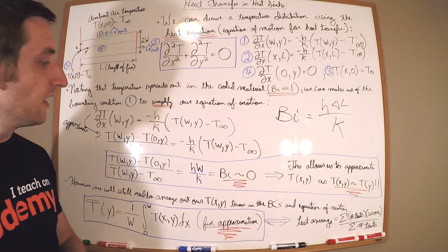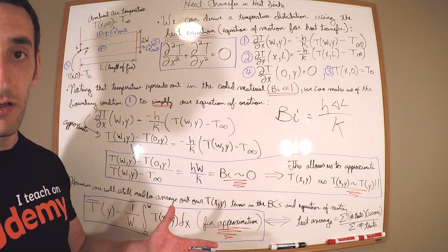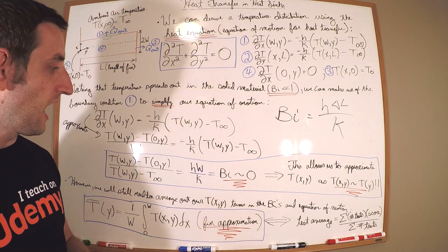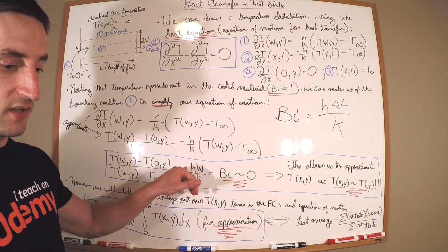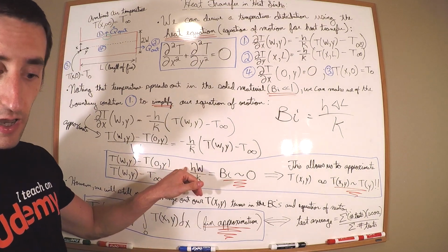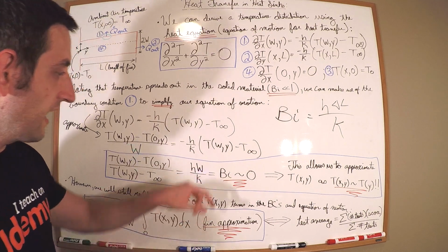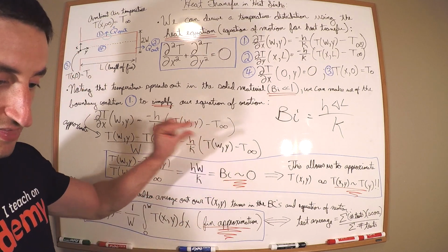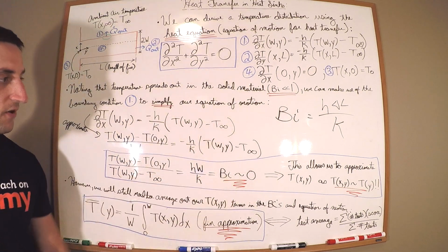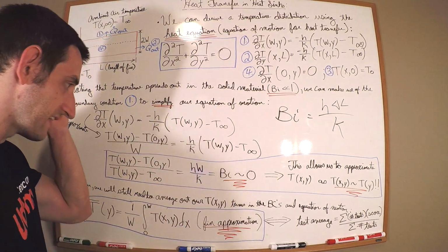situations at hand. We took a look at the solid material, the copper material, the conductivity. We used the heat transfer coefficient for this flow of air, this kind of situation. And we used the approximate thickness of the fin. We found that the Biot number is very, very small. And this means, what does this mean?